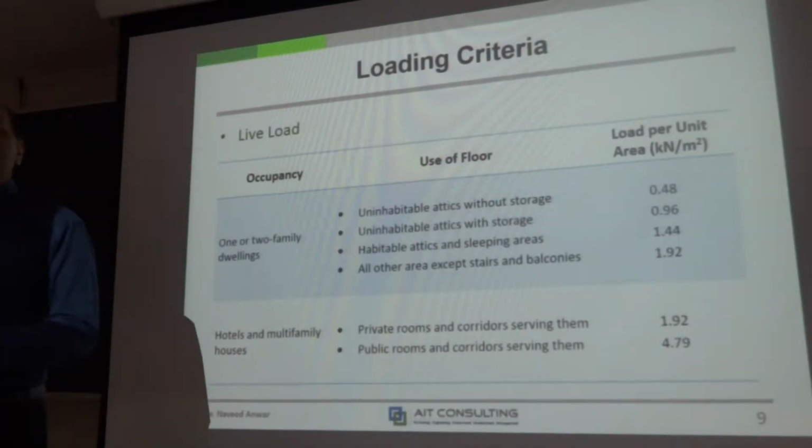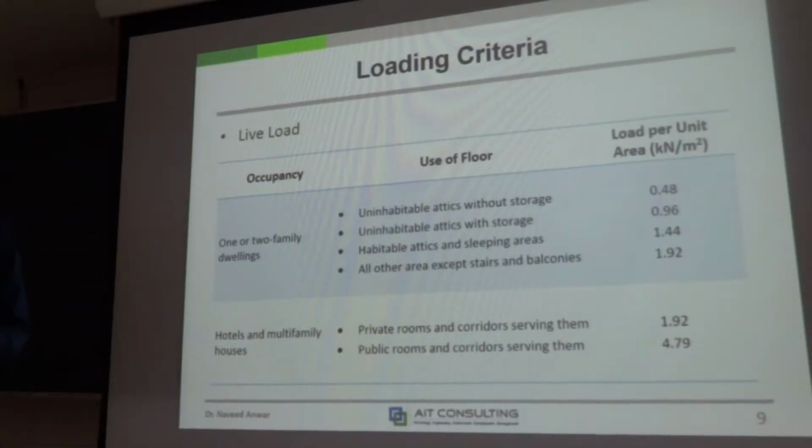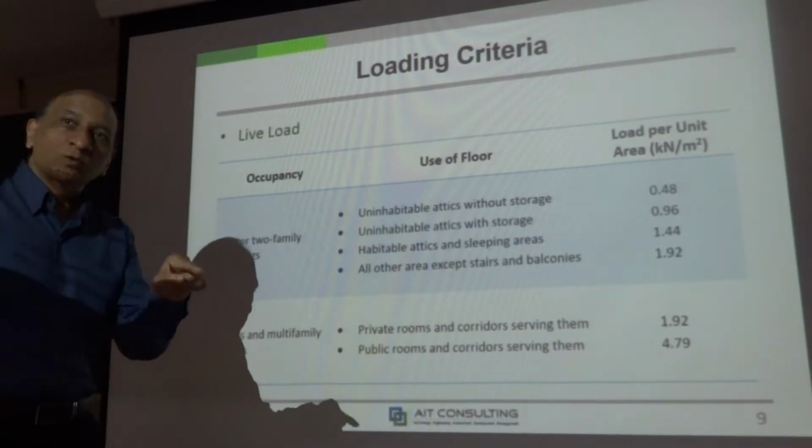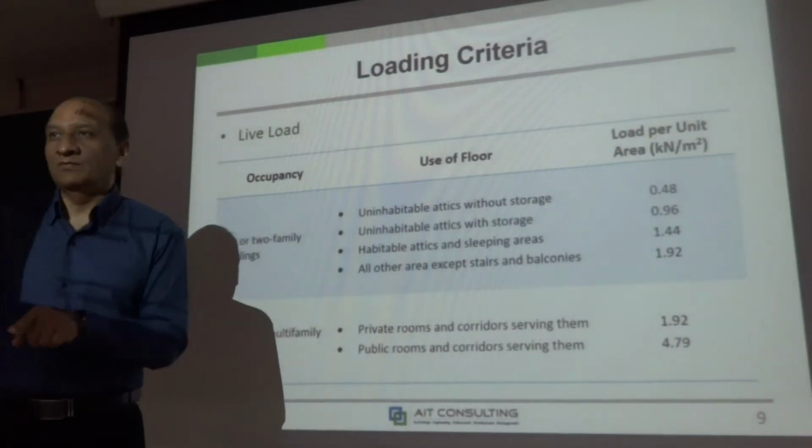But again, the problem is that we cannot be sure the use will continue. That's why there is a safety margin on that and load combination, which we will see later. But at least basic loads you must list based on the use that you know of that building. Which means different rooms will have different live loads.